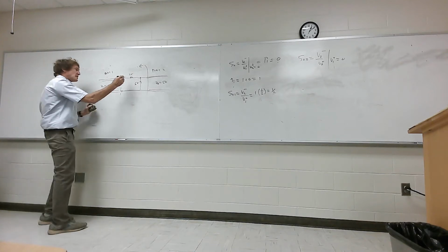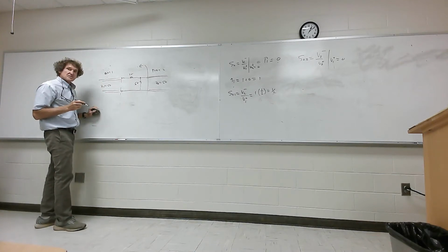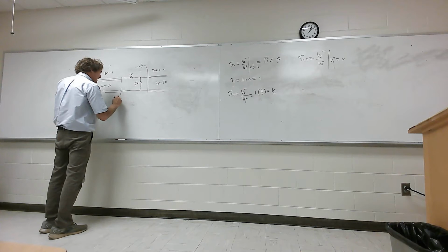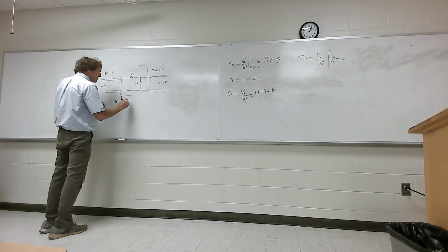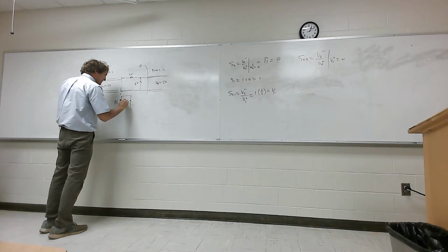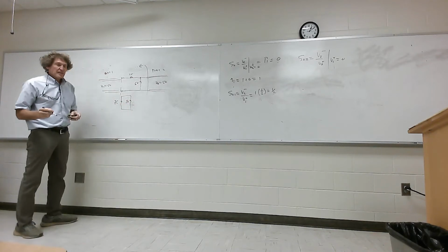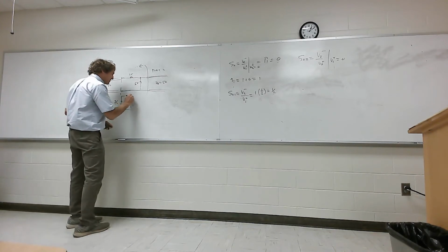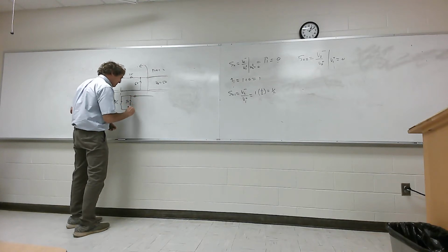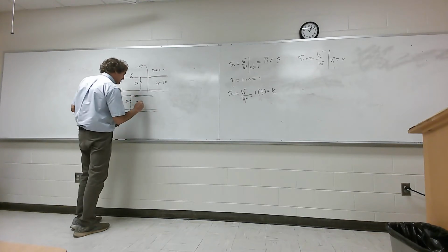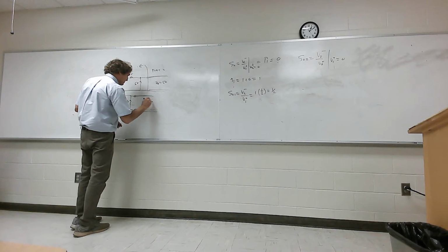So I have 25 in series with 50, or 75, right? So I have 75 ohms, and that's in parallel with 50, isn't it? Make sure you see this. And it's coming from 50 though, right? The Z0 over here is 50 ohms.